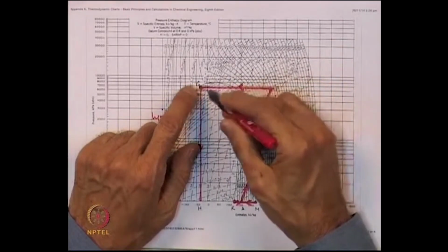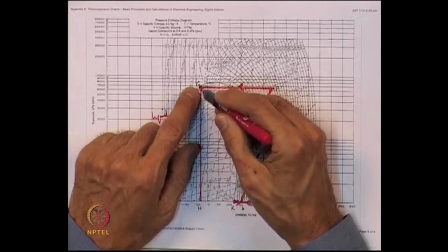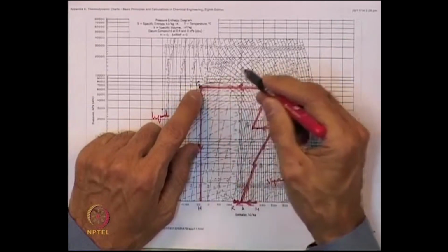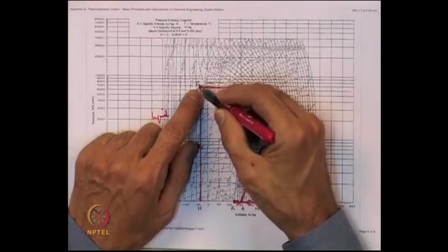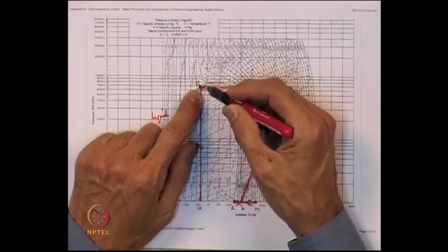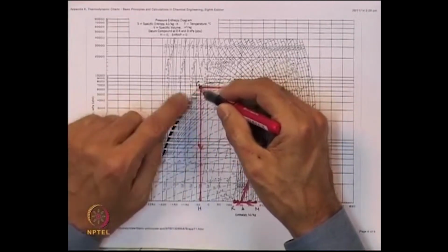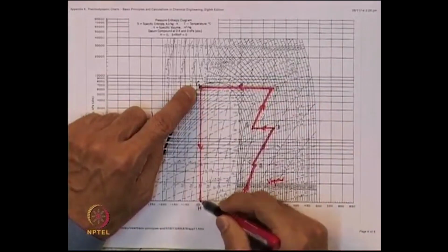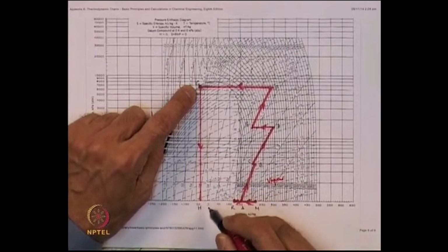Now, here there is a phase transition, you keep cooling it till all of it becomes a liquid. So, at the point G, essentially if you start with 1 kg at A of gas, at point G you have 1 kg of liquid at 6400 kPa. Then you do a throttling operation, it comes right down. The throttling operation is an isenthalpic operation as we have seen in theory.